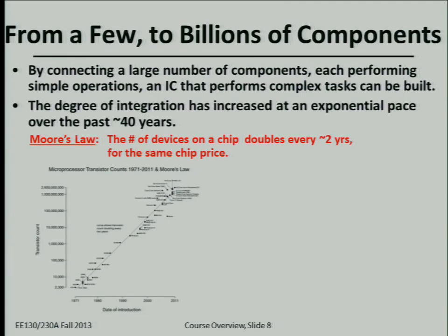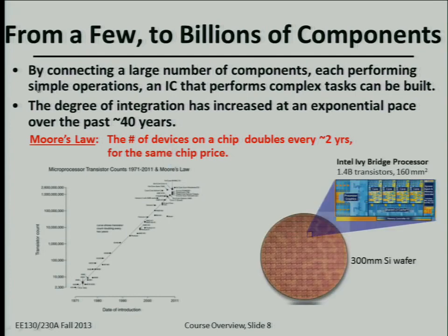So as an example, the display industry, making these flat panel displays, like now even for TVs that are really nice and thin, that industry, they have 1 transistor per pixel, per picture element. Okay, so that's an example of an integrated circuit technology or industry where they don't shrink the size of the transistor with each generation of technology. Instead, they actually grow the size of the chip with each generation of technology, right? So to sell more and more products.